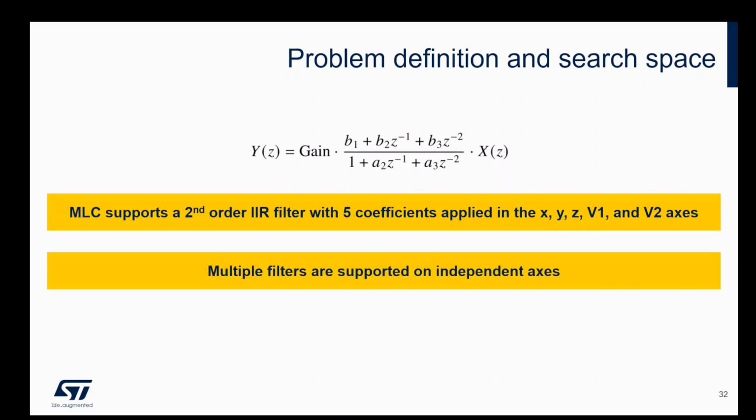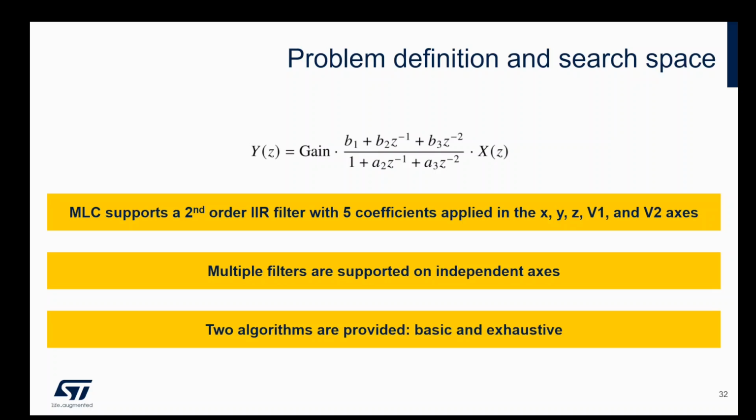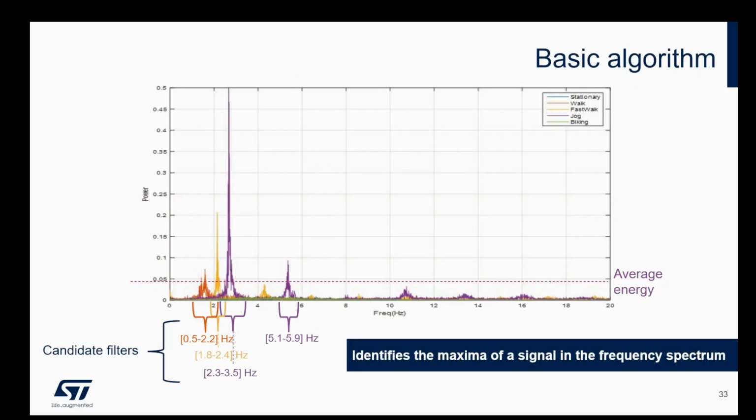And you can apply that to any of the axes, as I was saying earlier: X, Y, Z axes, a norm of the axes, or a combination thereof. And there are two algorithms, basic and exhaustive. So the basic algorithm, let me describe that using a power spectrum.